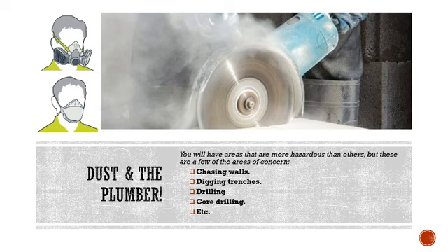Now, as we mentioned with plumbers, there's a lot of hazardous areas on a construction site, or even just in general when performing your plumbing works. But some areas of concern that we wanted just to touch base on this morning is looking at chasing of walls, digging trenches, drilling, and also core drilling. Now, these four areas are a few areas of concern that we've noticed while being on site. Obviously, the chasing of walls became a very, very big one because we are in a confined space, perhaps inside a room, and there's no adequate ventilation for the type of dust or the amount of dust that is going to happen in that room.